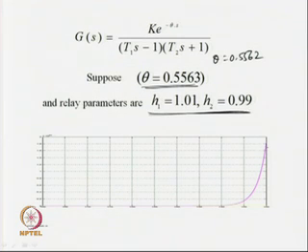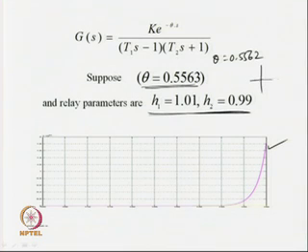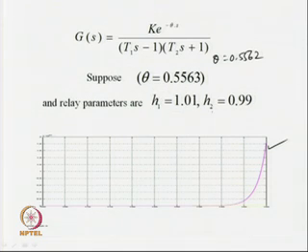Here you see the output is blowing out and we are getting very high output. That means the relay control system is unable to provide us a stable limit cycle output. So, in place of getting a pattern of this form, I am getting nothing. What we infer from this is that there is some constraint associated with unstable systems or processes in particular, that must be maintained, otherwise one may not expect stable limit cycle output from unstable processes. How to overcome this limitation, we shall discuss later on.